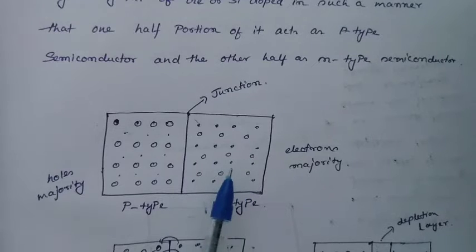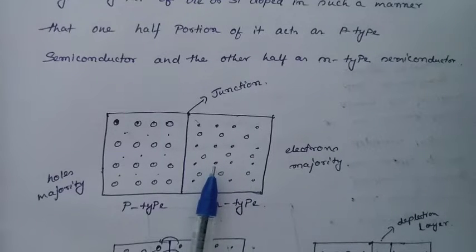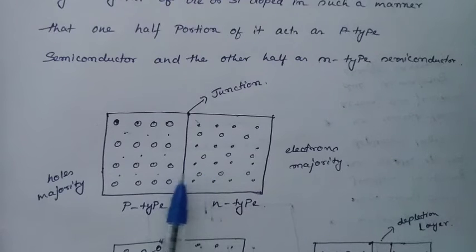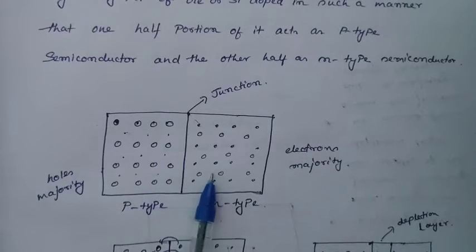materials. This PN junction is the key to all the semiconductor devices, and it can be used as a rectifying diode, or another use is the transistor. Here, there are two important processes involved during the formation of a PN junction. One is diffusion and another is drift.